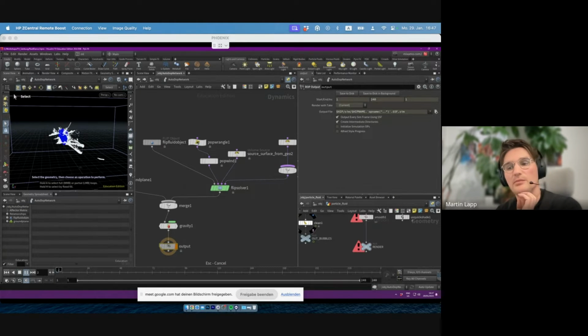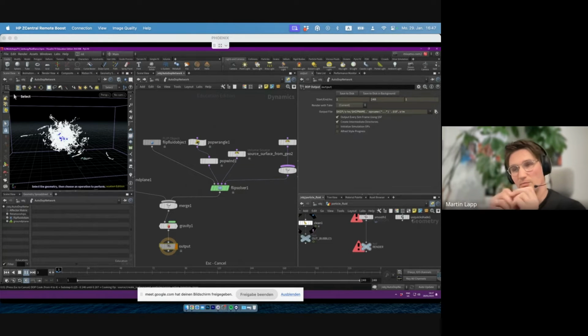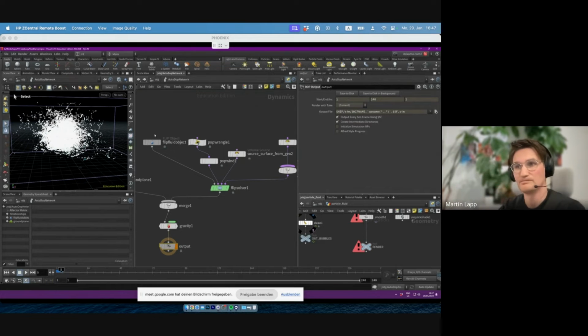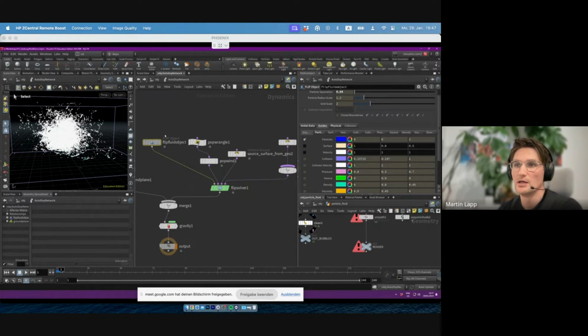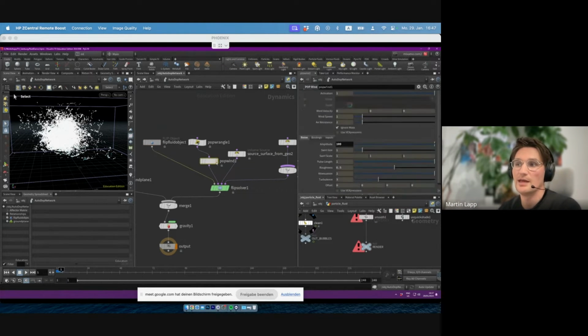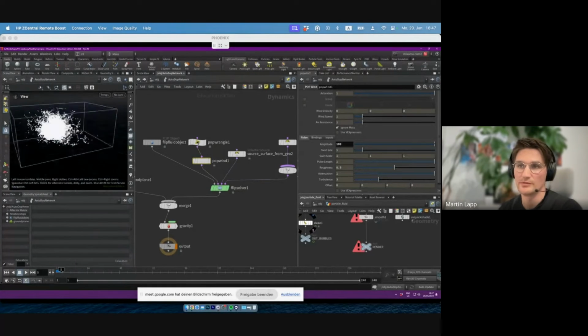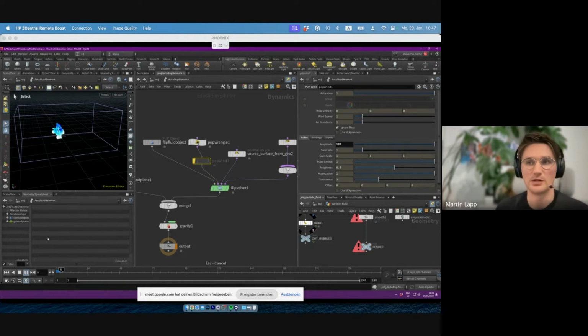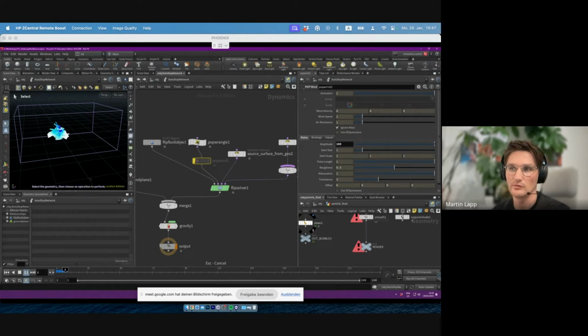So now you can see the initial frame is even completely exploding because it now calculates the vector between my initial velocities, which are quite high already, that you saw previously of that noised up sphere. And then it adds into the mix this pop wind, which is this ambient wind, which has an extreme amplitude. And that's why the resulting vector of each point is just way too much. So it completely loses its fluid shape.